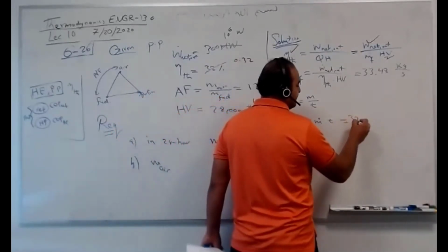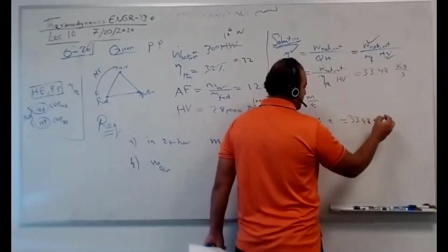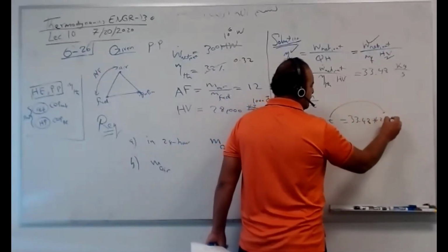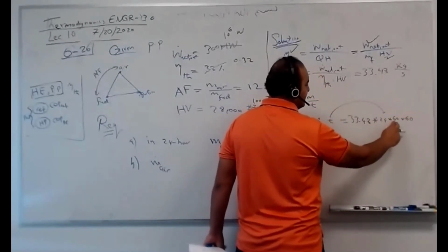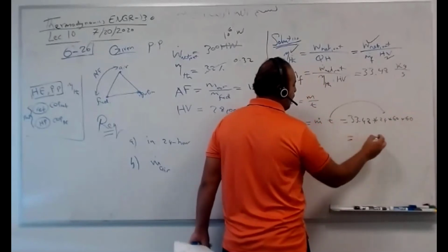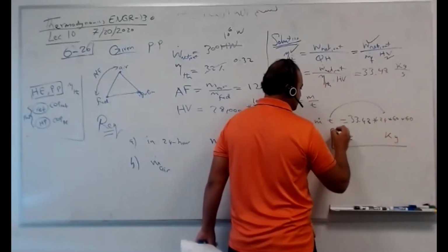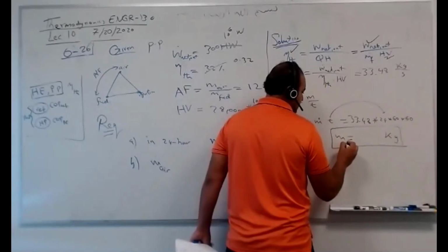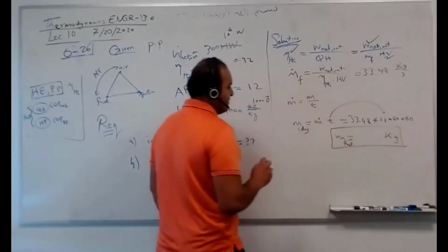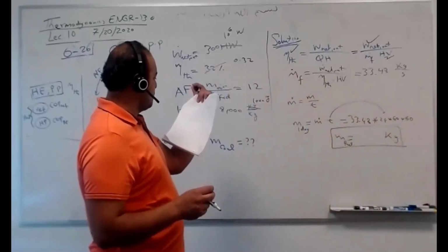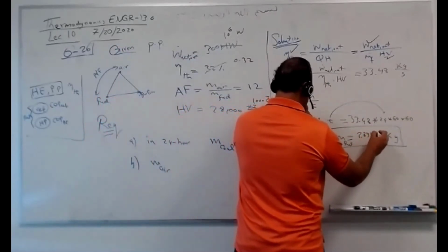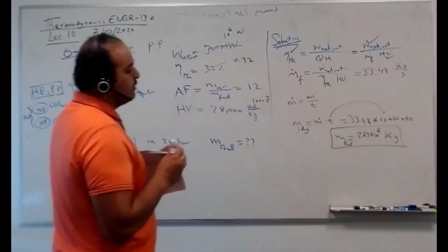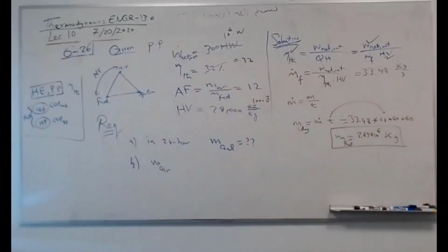So it's M dot times 1 day, 24 times 60 times 60. 24 hours, 60 minutes, 60 seconds. So you can obtain how many kilograms you want for this fuel. Not M dot, it's M, mass. It was 2.89 times 10 to the 6. Oh, wow. Almost 3,000 tons. Almost 3,000 tons daily.